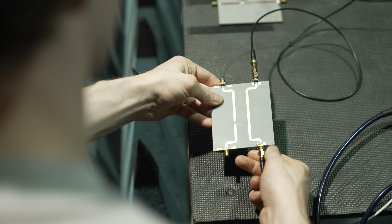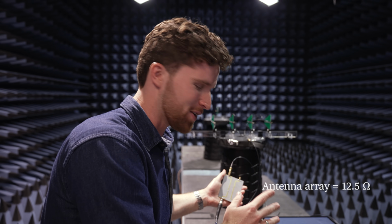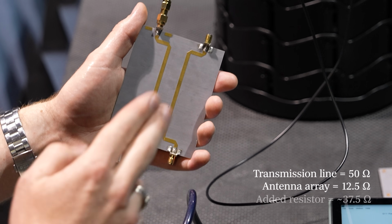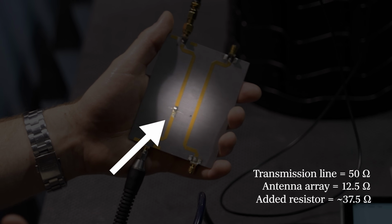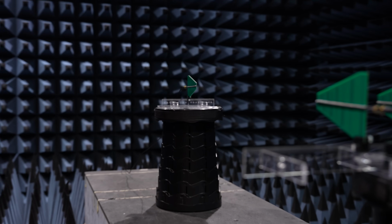Indeed, in real life, when we checked, the resistances didn't match. So the antenna array is at 12.5 ohms, and the transmission line is at 50. So what we're gonna do is we're gonna add this 37.5 ohm or 40 ohm resistor to try to bring it up so that they match. And we'll see what happens to the power.